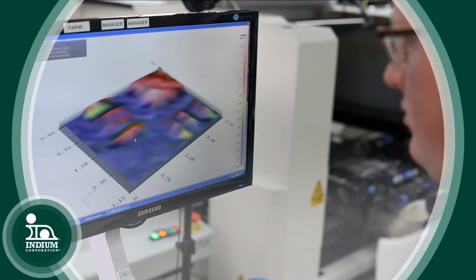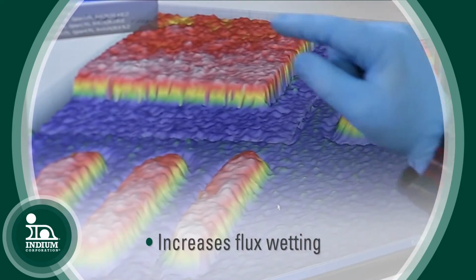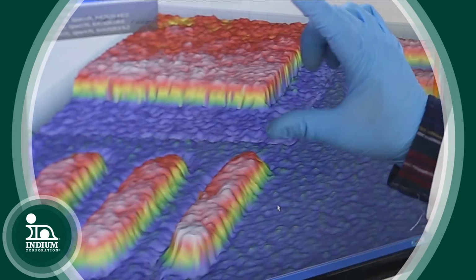One is if you can design a flux which will not have outgassing at a higher temperature, you cut out the source of the voiding. The second thing is if you design a flux which is very good at wetting, then the flux cannot hide inside the molten solder joint. That's another angle you can solve the problem of the voiding. So we design the flux basically from those two angles, from the material side.